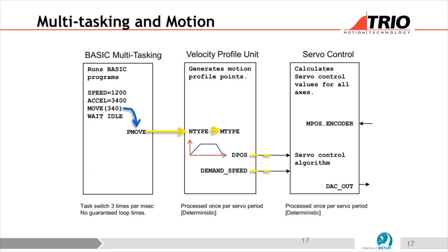Actually, we had experience with an application. They call it a transfer machine. The transfer machine uses several multi-axis parts. For example, 2 axes do the drilling. The next station, the work is moving, exchanging position between the different stations. And the next station does some tapping, for example. And the next station does some engraving, for example. So the same part is exchanging stations in the machine. And then finally, the final piece goes out of the machine, unloaded by robot or something like that.